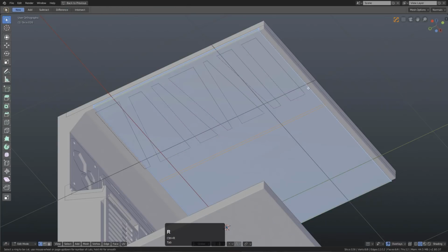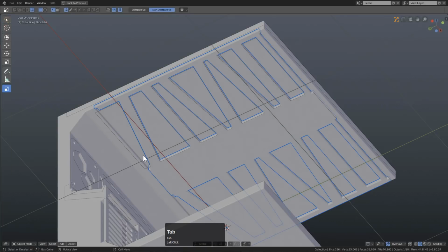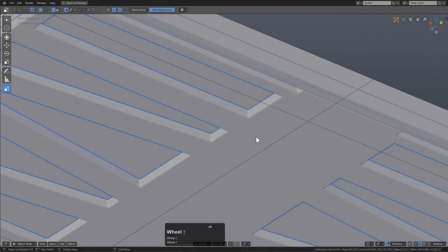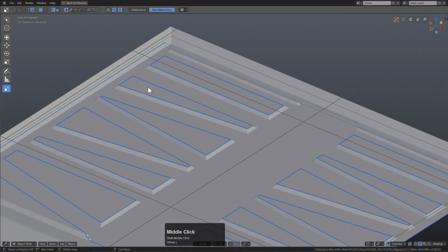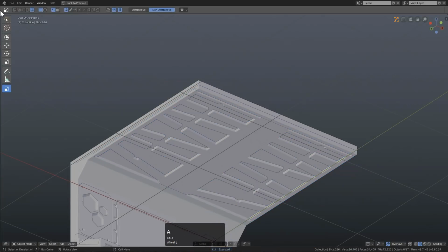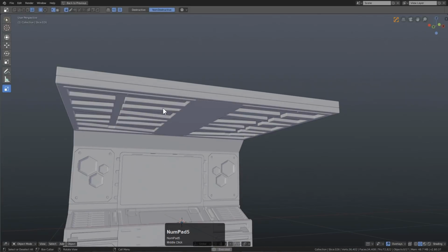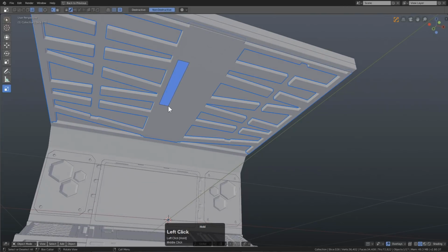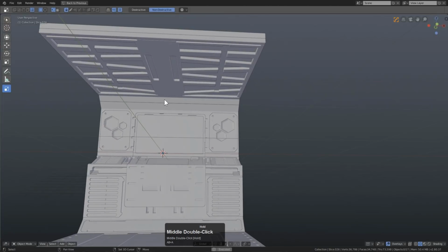So right here, I'm going to tap into edit mode. I'm just going to put a single loop cut right here, and that's not a problem anymore. Support geo goes a long way. In a way, I almost see the bevel modifier as a sort of auditor. I'm still just stuck in blue box today. Let's get out of that. It's like a sort of auditor where if the geometry isn't completely efficient, it'll cause some mesh catches to happen.